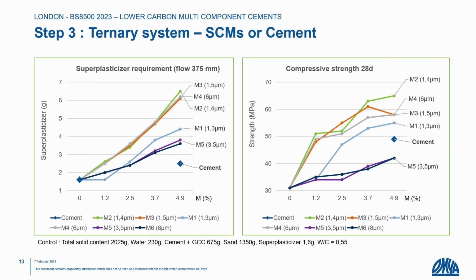But in the meantime, when we go here on the figure on the right, we can see the added value of this increase of cement concentration. We perform the system in terms of compressive strength, but we can see that some of these calcined clays have higher performance. This is just an illustration that we have a huge interest to combine minerals, in this way, to optimize the packing of the system, the stability, the flow, and so on.